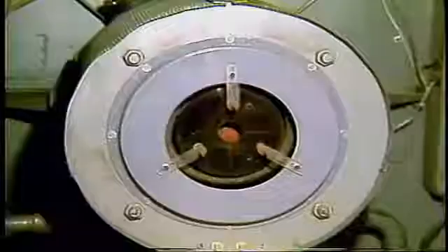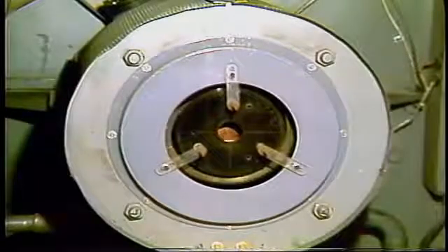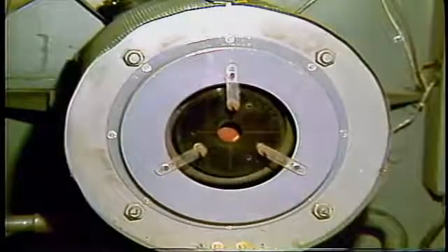Of course, for a short overnight shutdown of the machine where generator maintenance is not required, the generator remains charged with hydrogen with the seal oil system in operation. To prevent excessive leakage from the seals, it is important that the shaft rotate continuously on the unit turning gear. It is quite apparent that operation of the hydrogen cooling system is much more complicated than generator cooling by air. You must become thoroughly familiar with the operating procedures for your particular installation.